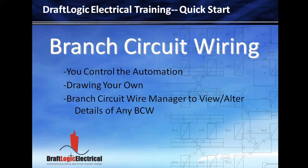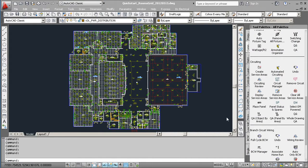If you desire, DraftLogic Electrical will also figure out multi-circuit branch circuit wiring home runs for you and draw all of the branch circuit wiring interconnects between the various devices, deciding on wire sizes, wire counts, and placing your home runs for you. You control the automation through the parameters, and you can also draw your own detailed branch circuit wiring or modify the automated branch circuit wiring using the Branch Circuit Wire Manager. Branch circuit wiring is optional.